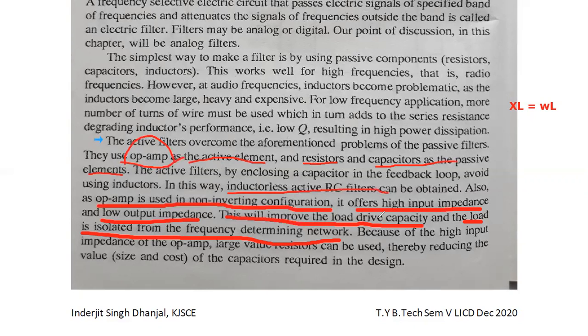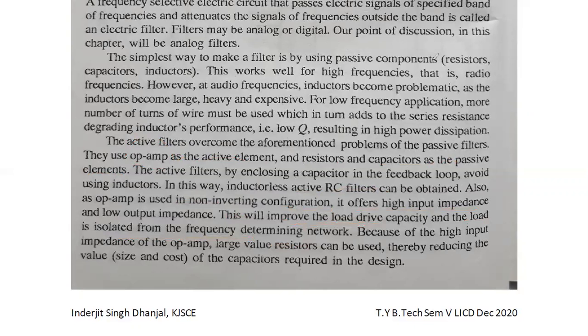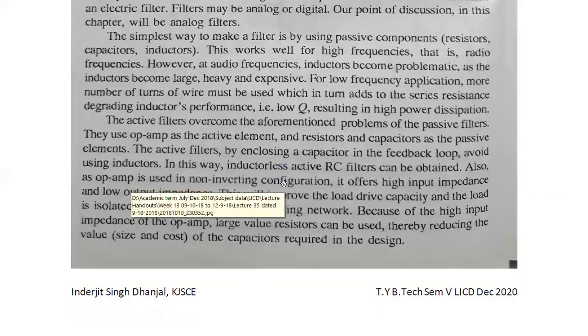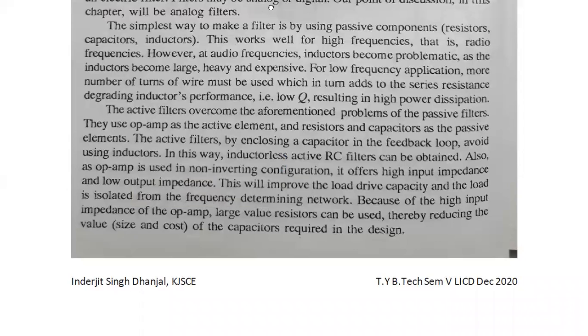Now, because of the high input impedance of the op-amp, large values of resistors can be used, thereby reducing the size of the capacitor required in the design. So we can play around with the resistor values, keeping the capacitor value intact. So this is a brief introduction of filters. Now let's move on to the next topic.